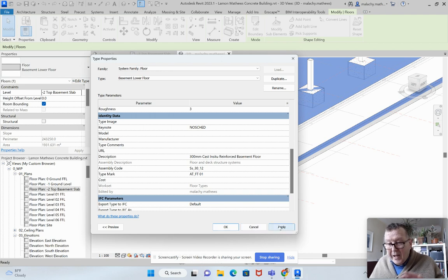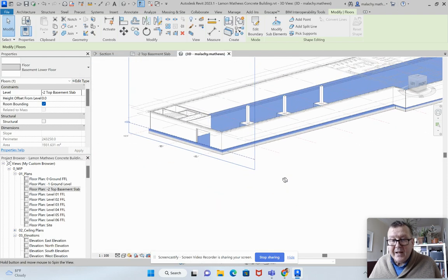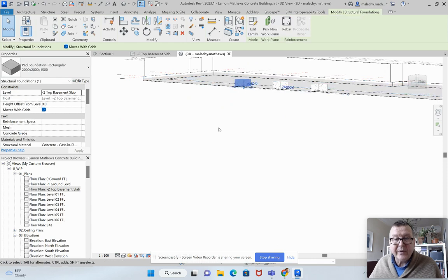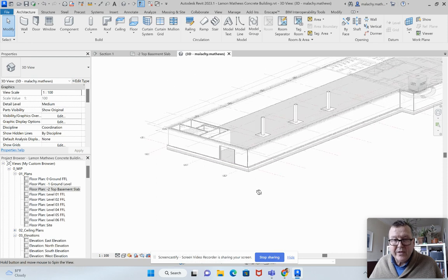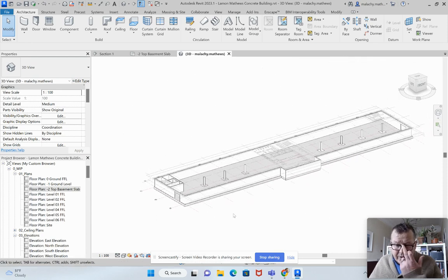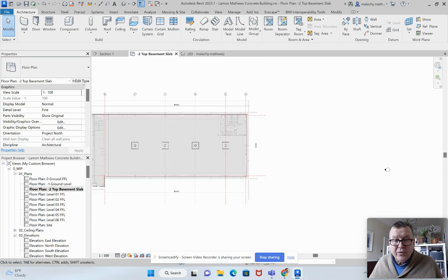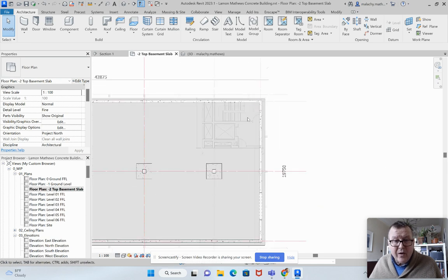So again, all your elements that you create, you need to be putting in this type of information as you go along as well. Okay, and then perhaps the last thing we need to do here is get this one, the pad. Look, that pad is going to be part of the floor, so we don't need to put info in with that one there. So that's how I've got my basement started. What you need to do is make sure that now you've got all your walls in and they're all correct. Watch out for part 2, and I'll continue on with this.